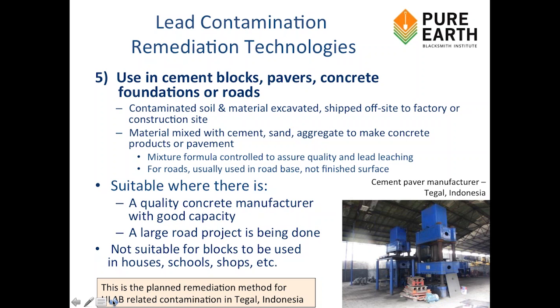We generally do not consider this as a suitable technology where the concrete blocks may be used in houses or schools or other places where any shedding of particles from the blocks would present an exposure risk. So generally foundations or commercial structures, industrial structures.